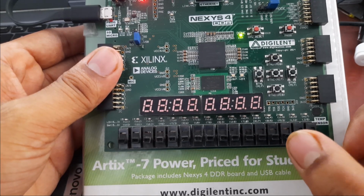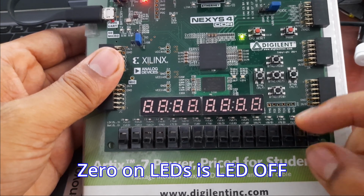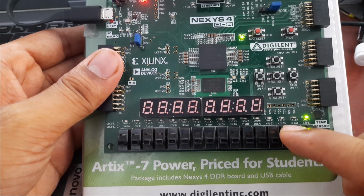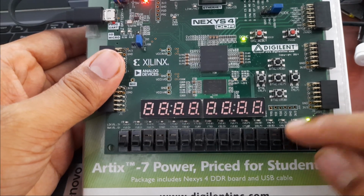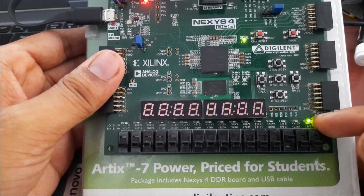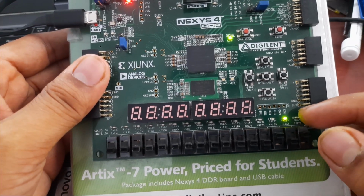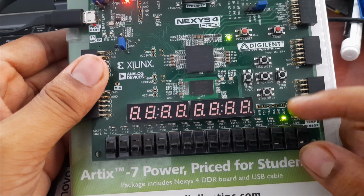Right now the input is 0, so it doesn't matter what I select, you won't be able to see the routing. So I'll keep the input at 1, so that you can see which output is taking the value of the input. Right now 0 0 is selected, so the input is fed to the output Y0. Now I'll do 0 1. As you can see, the output Y1 is now connected to the input.